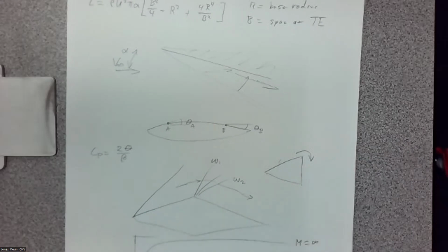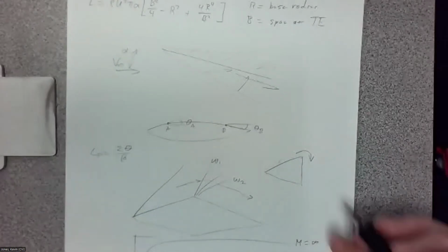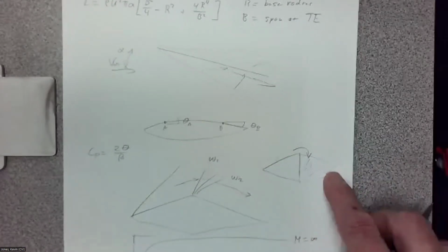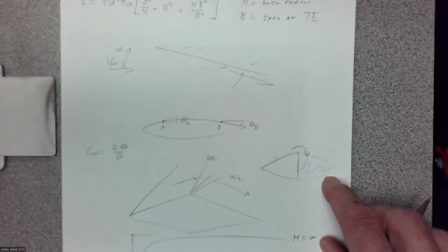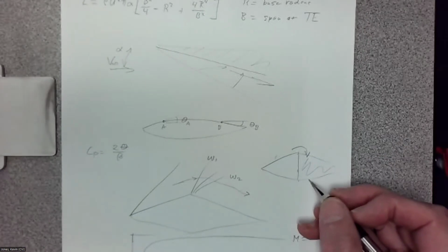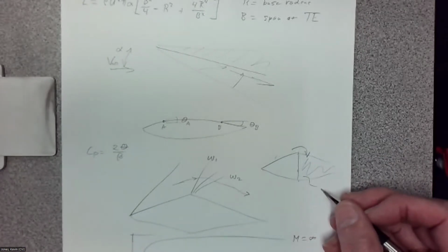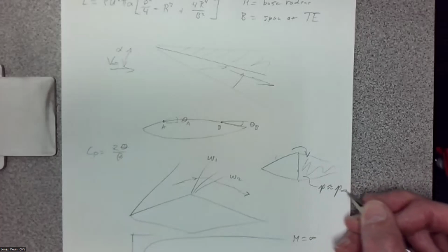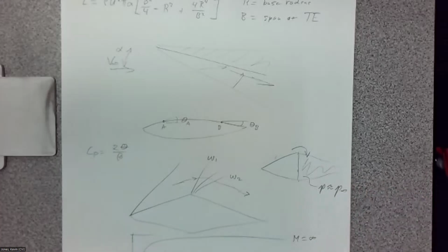It's going to go to Mach infinity, which means absolute zero pressure. It won't do it. And so at some angle, you'll end up getting a big old stalled mess back here. It's just really hard to calculate. But in the end, the pressure is close to P infinity in that kind of boat tail region.